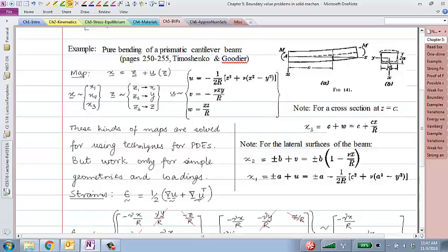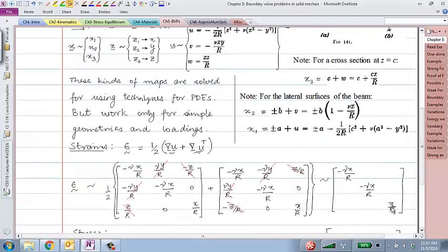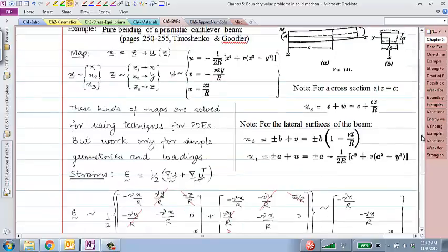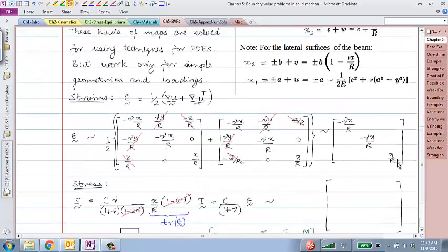So the strain field is clearly not a function of y and z. It's only a function of x, where if you go in this direction above or below the neutral axis, you get positive strains, tension. You go above the neutral axis in this direction, that's compression, negative strains. So that kind of strain field makes sense.